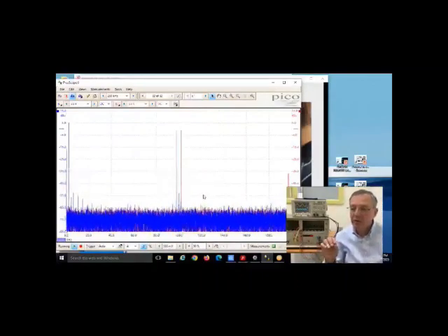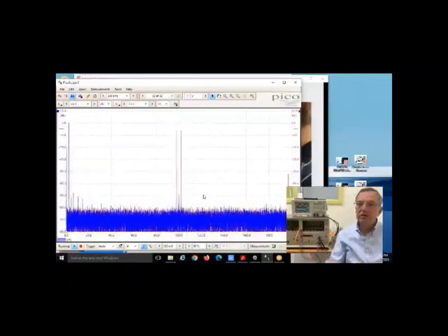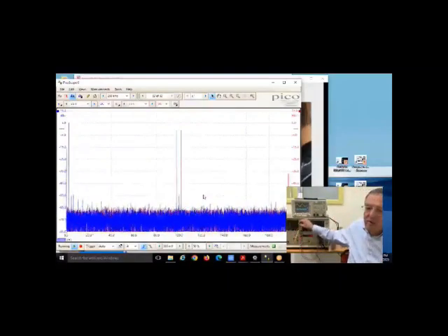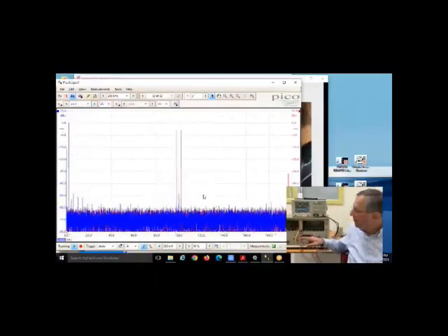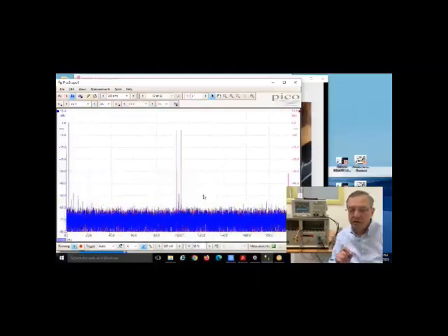So you see, TIMS is not meant as an ideal system. These are real signals with DC offsets, bandwidth constraints, phase constraints, so the student can look and learn what are they actually looking at? What's the difference between DC coupling and AC coupling? And you can ask the student, measure these signals and have a look. Why is that happening? What's the DC? How much DC is there? And there's probably 3 or 4 millivolts of DC coming through.